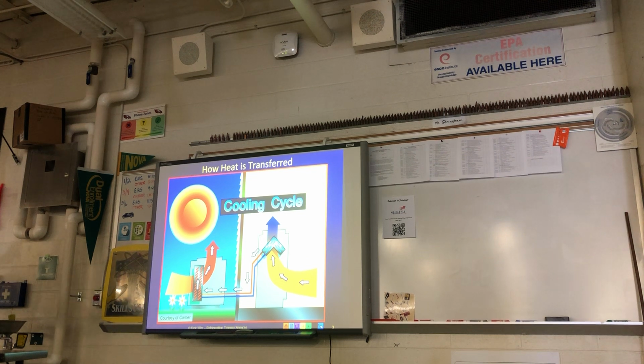So if that's the supply where it blows out, where am I sucking in at in this room? Take a look around. Through the vents? Not these vents. These are all blowing out. And if you notice, I lose about half of my airflow here, so they had to reduce the size to keep the pressure up. But where would it be sucking in at? Where's another place that you see that it could suck in?